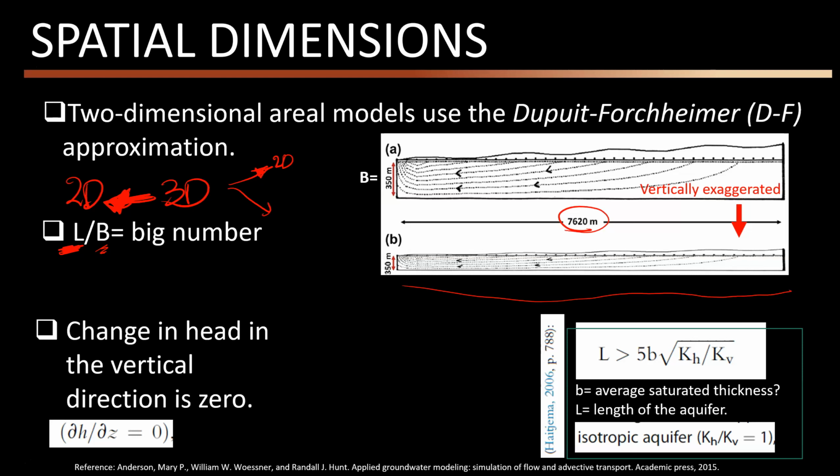But if you scale your conceptual model correctly, you will see that assuming that the streamlines are almost parallel and ignoring the small vertical gradient components of the flow is a very reasonable and practical assumption. And as you see here, at least we can say that in the big chunk of the aquifer or the conceptual models that we are looking at, this is a valid assumption.